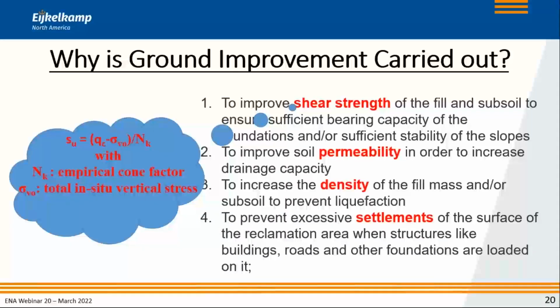Let's first look at the shear strength. I have to give you a few equations, and I'm not saying that after this there will be an exam where you have to learn all these equations or be able to regenerate them. But when you look at the shear strength, it is really a function of the tip resistance minus the total in situ vertical stress, divided by some empirical cone factor.